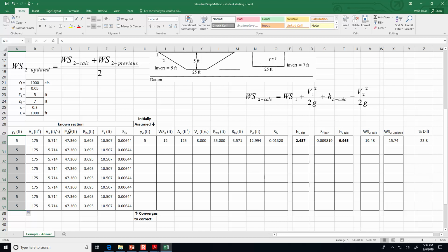Okay. Yeah, so we did it to that one. Let's see, where else? Anytime we have a reference lower than 26, for instance this one, you're going to need to anchor that. The way that I do it is function F4, and it automatically puts them in. And this is a reference to one of those, so function F4 there. Here, this needs to have the dollar signs in there.